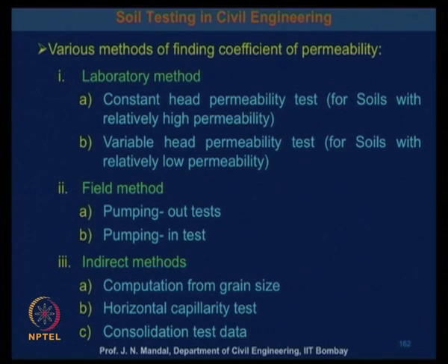Apart from the laboratory method and the field method, you can also obtain the coefficient of permeability by indirect methods, that is, computation from the grain size, the horizontal capillary test and consolidation test data. So, there are various methods for the determination of the coefficient of permeability, and as I said, this is a very important parameter for soil mechanics or geotechnical engineering.